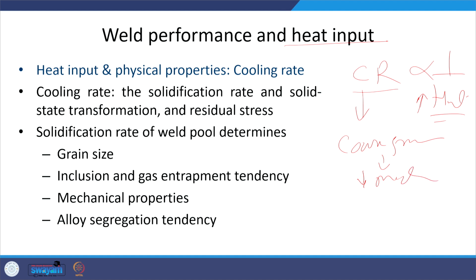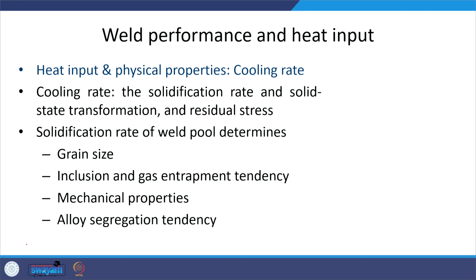The cooling rate for a given heat input will depend upon the thermal conductivity and the section thickness of the material. So the weld performance, depending on the heat input and the physical properties, will get one set of cooling rates, since the heat input directly affects the cooling rate. The cooling rate in turn affects the time a weld metal will take to solidify, so the solidification rate, the solid state transformation and residual stresses.